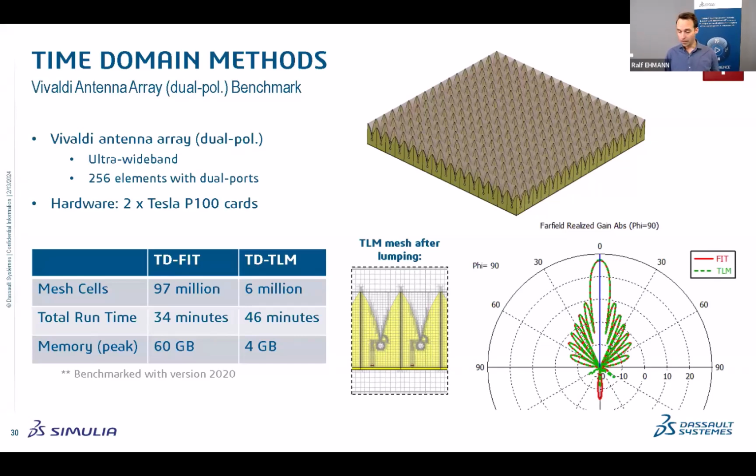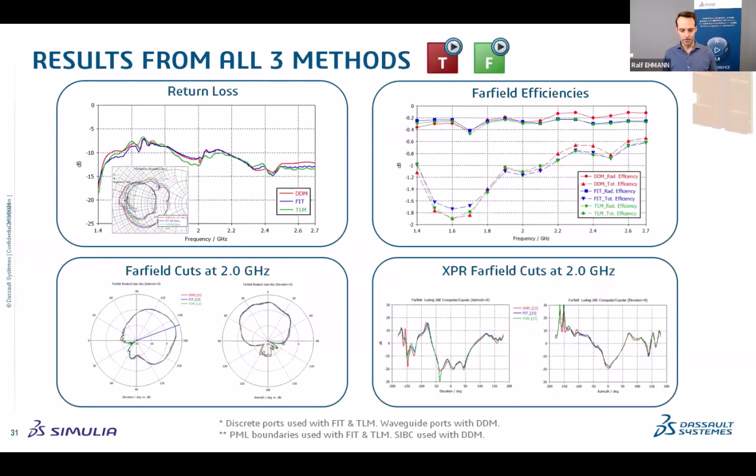Talking about solvers and how they compare in terms of fidelity, because I think for those of us also used to measuring, sometimes it's good to go and measure as well. I can tell you we have many methods, and the point is you can actually get these stacked up against each other and really with surety show that results are converged before you prototype anything. So in this case, we have some results from a benchmark we did for a customer, so a confidential model with a lot of detail in it, I can tell you. You can see we used the domain decomposition, DDM, FIT, and TLM,